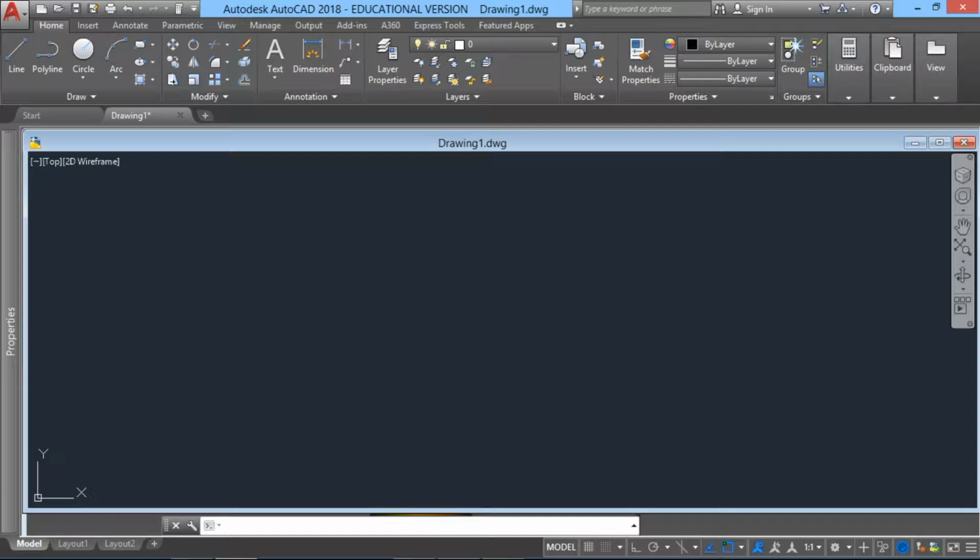Inserting the A3 title block was already provided to you in recordings, along with demonstrating grip editing and means of resizing and moving the viewports. We already talked about the viewports in paper space and scaling the floor plan viewport to 1 to 100.